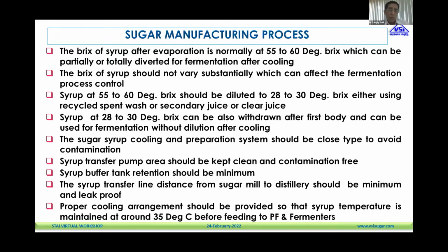The sugar syrup cooling and preparation system should be closed type to avoid any kind of contamination. The syrup transfer pump area should be kept clean and contamination free. The syrup buffer tank retention should be minimum. The syrup transfer line from mill to distillery should be minimum, and it should be leak proof.